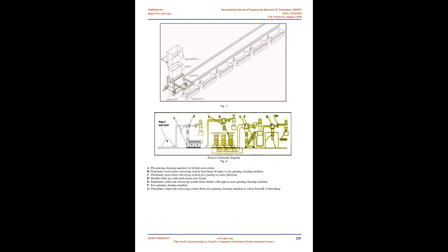4. Ginned cotton from the storage hall is conveyed by pneumatic conveying system to the press hall for making a compacted cotton mass called a cotton bale of 165 to 175 kilograms, each on a hydraulic press. The cotton is fed manually to the press, hence the quantity of cotton per bale varies between 165 to 175 kilograms. Even the machinery setup of a modernized ginning and pressing unit discussed above has many limitations, as discussed below. These limitations are overcome by implementing automation.